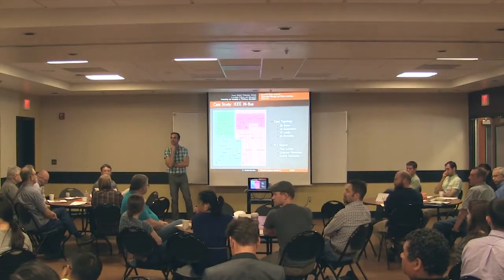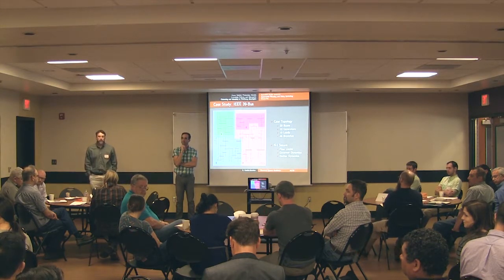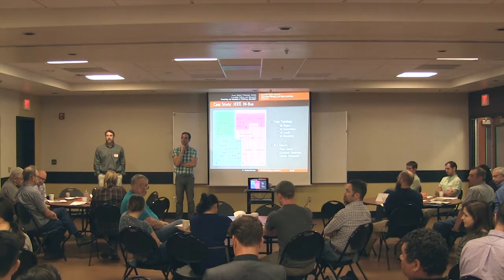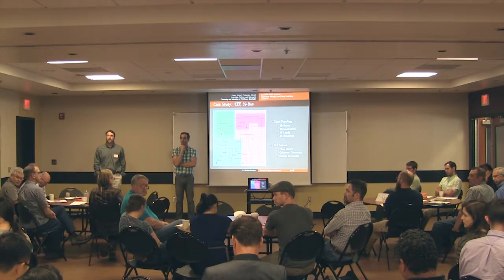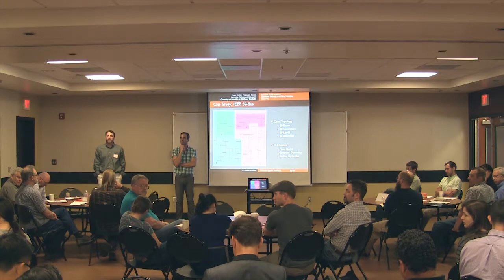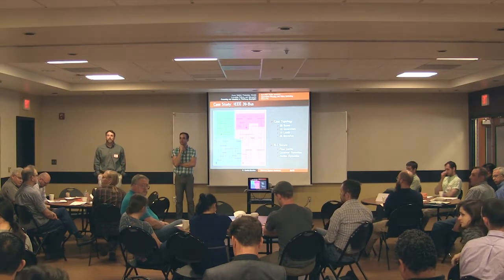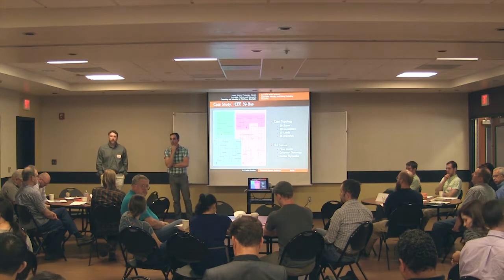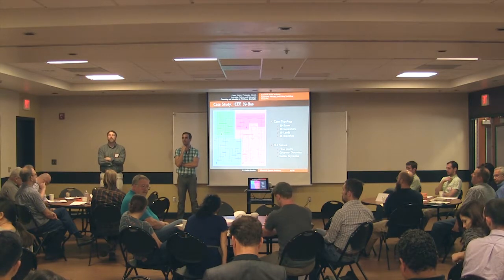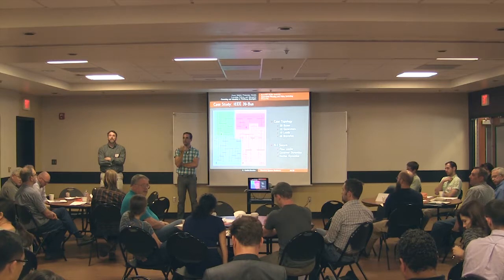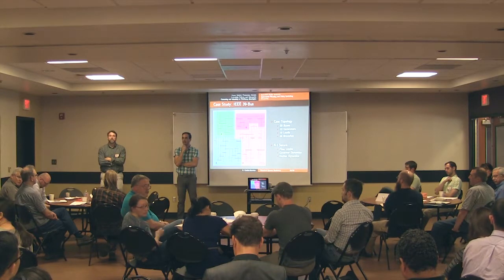Yes? An interesting offline conversation would be how to take this really cool analysis and compare it to the operational implementation on a nuclear-powered warship. Because we do a combination of failure modes and effects criticality analysis, and load shedding. On a Trident, it's all manual. But by design, we have the non-vital bus, the vital bus, the instrumentation bus, and the prioritization of loads might not be obvious. One, you've got to keep the reactor up, except if you don't, but you've got to be able to shoot a torpedo or the missile without a doubt. So we use the concept of graceful degradation in a combat system. And I think some of this would be really fun to play with in an unclassified manner, of course.